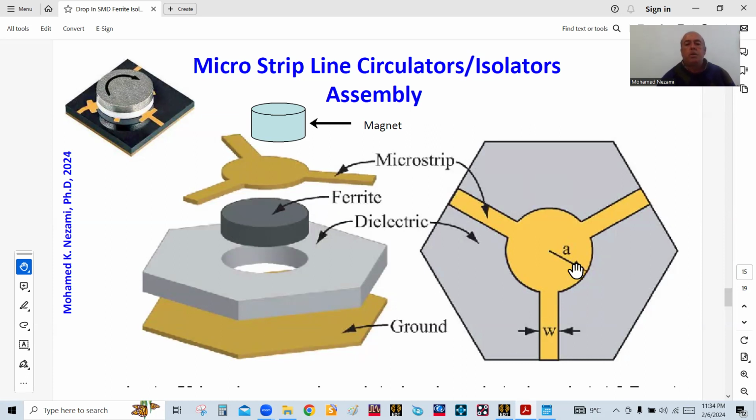So the idea is that, given an operating frequency range, the way to design this is there's a set of equations where at the end, what you come out with is the diameter of the ferrite disk, and the height. Of course, you pick the material, and the thickness of the material is limited by the vendors. For instance, you go to Rogers and grab one of the substrates. Let's say the one I'm using right now is Rogers 4003, which is appropriate for, say, X-band, Ka, Ku band circuit boards. You can see that the thickness is limited to anywhere between 8 mils to 60 or 80 mils or so, okay? So you can't go very thick on this. You would have to use some other technology to get the thickness.